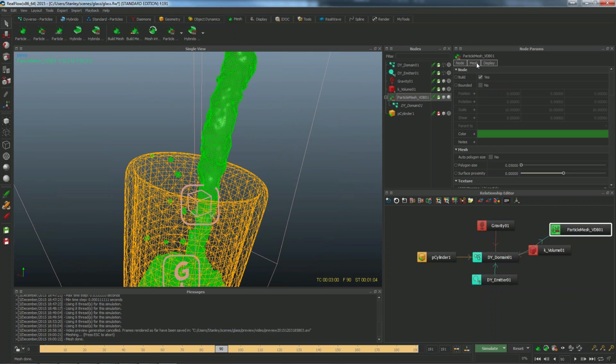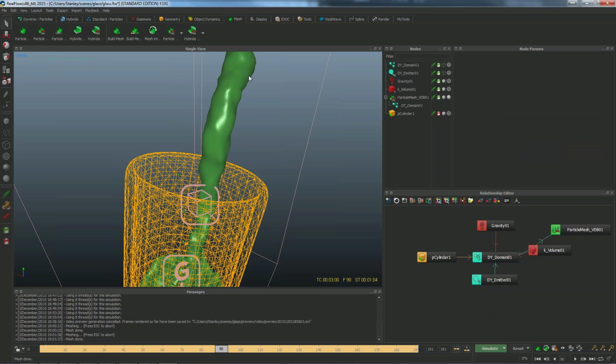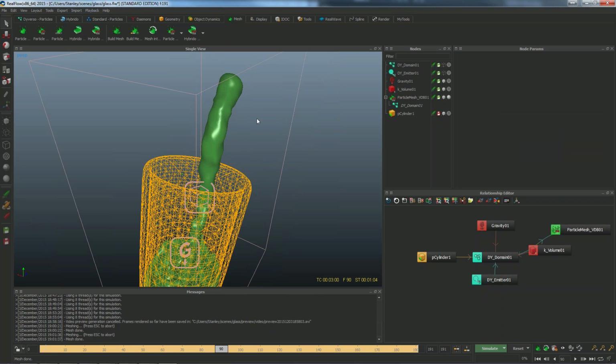look, that shape. First of all, in the mesh tab, we can add a mesh filter, a general filter, and add a few steps in order to achieve a certain relaxation factor. This is the factor, and this is the steps to achieve such factor. So if I just click on build again, here you see that the mesh is much more smooth actually.